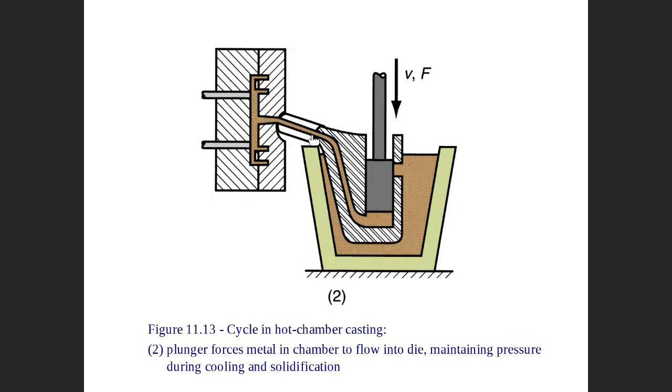The most important thing here is that we apply pressure. We maintain pressure until solidification happens. This pressure is very important to maintain until solidification is completed, because while applying pressure, you're forcing the liquid to fill the cavity perfectly, every tiny detail. It fills under high pressure because the pressure is applied by the plunger, as you can see.